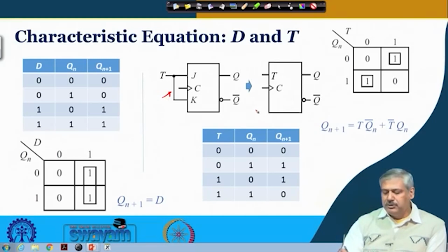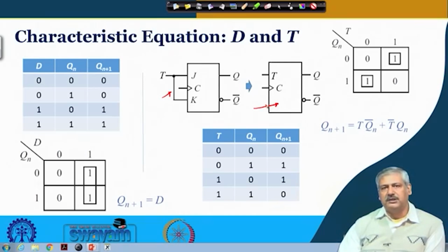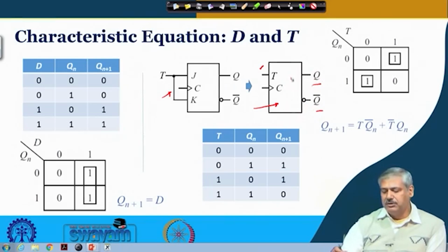So, all those things are pushed inside the logic circuit within a particular group where all the elements are there, and then what we get is a single input flip-flop. Of course, it is clocked, positive triggered and all, and the Q and Q bar are outside, that is why this bubble is there. If they are inside, the convention is not to put the bubble. I mean, if these symbols Q and Q bar come inside, the bubble is not put. We have discussed this before. So, this is your T flip-flop.